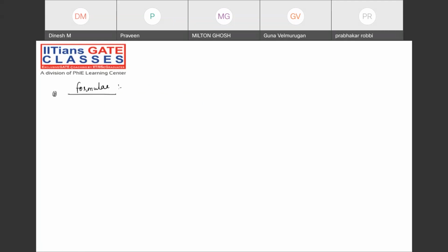So this method will be easy when the bending moment diagram is easy. When the bending moment diagram will be a parabola, we need to find the area of the parabola in that case. Very first case will be this thing. The moment I'm going to apply for the length L, note on the formula, slopes and deflection. Theta B will be ML divided by EI, and deflection will be ML square divided by 2 EI.